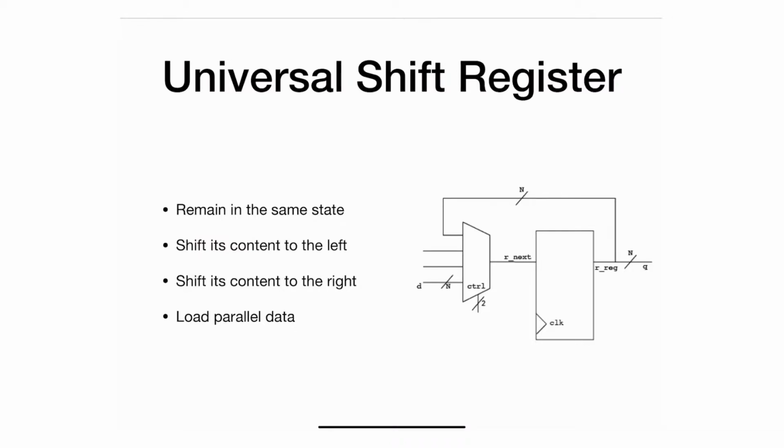This is very common when we're talking about communication systems, and we're going to see it later. For example, I have a register in here, and I have a register in here, and in order for me to avoid connecting them by 8 wires, I can connect them with a single wire. I can load these with 8 bits in here, and I'll have all 8 bits, and then I'll send them over the wire one at a time.